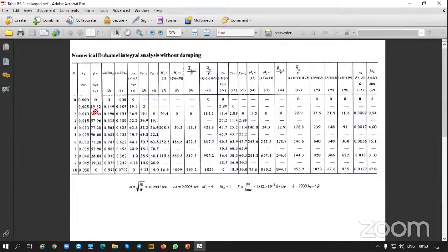where we are just having this column 21, which is the displacement times k, stiffness. Okay, so we have subdivided our time for each ordinate from 0 to the number of ordinates that you are going to determine, because this n will be determined, of course, by the time interval that you have chosen. And you have chosen a time interval of 0.005 seconds. So you are moving from 0.005 all the way with that interval up to the last time interval 0.05, the end of the load application.